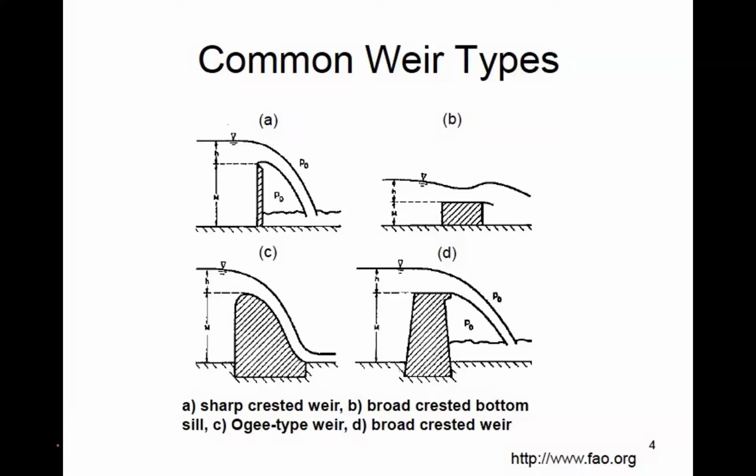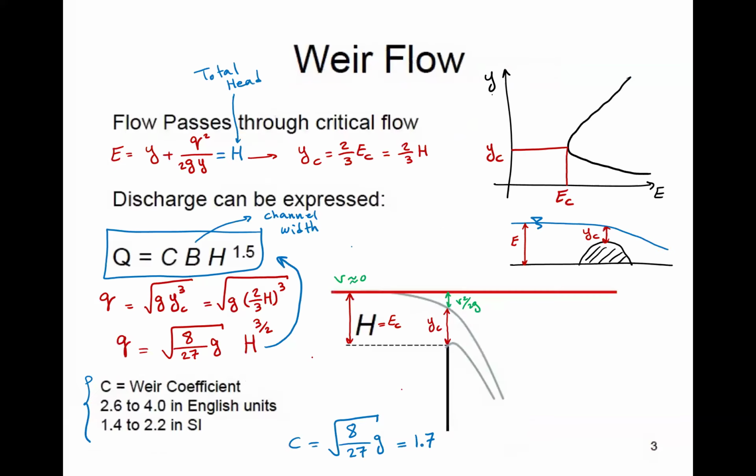They could be a very simple steel plate that you stick in a relatively small channel, let's say, to measure flow. I'm going to go back for a second, because the whole point of this weir structure, the hydraulic control, is that if you measure the upstream water level H, which is the head on the crest, so the distance from the water level upstream to the crest, that's as simple as that. If you measure H, you can calculate discharge.